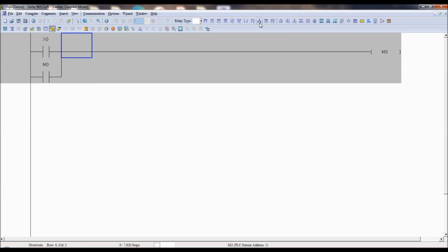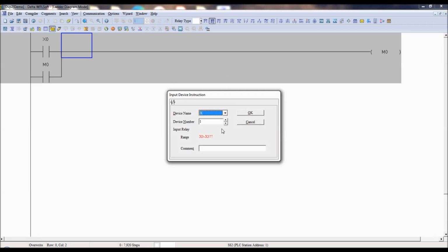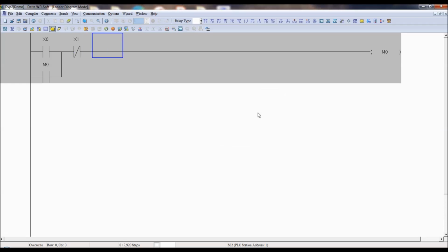It's connected. Whenever you want to erase the data of M0, you should break the continuity, that is normally closed X1, and we call it stop. I think this is understood. So now, by operating X0 once, M0 is continuously on.